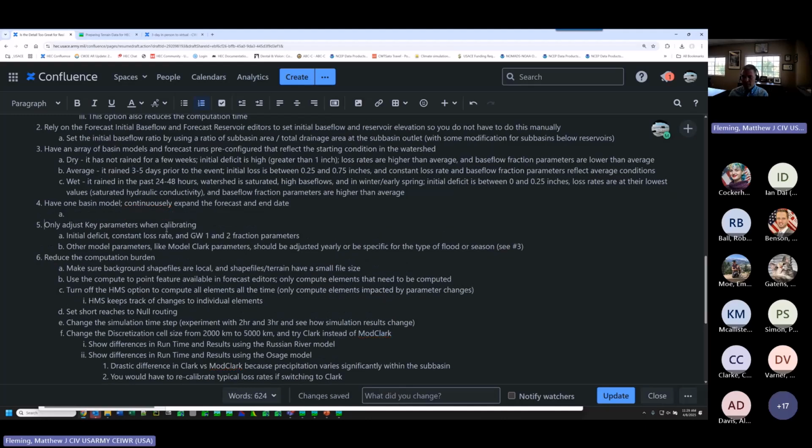Okay, you said some good things there. Let's dive into what you just said, Kevin. Let me make sure I'm capturing this right. You prefer one basin model, but then each day or each week, you're just extending the end time and the forecast date. Is that right? Yep. And then I'll tweak the calibration as I go to match what was observed from my last forecast to the current time.